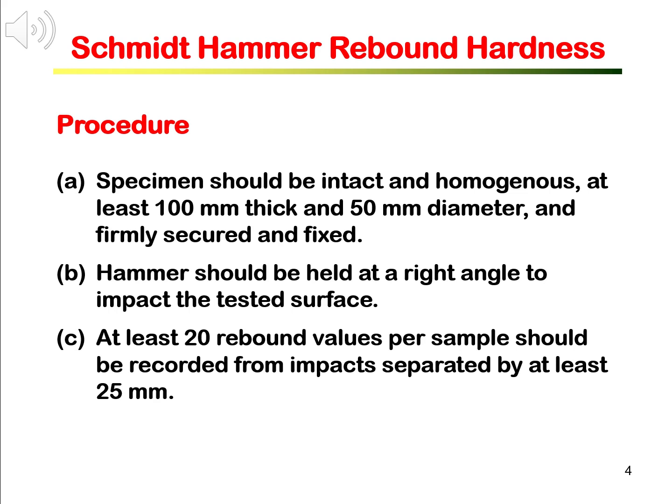Hammer should be held at a right angle to impact the tested surface. After the impact, the hardness reading is shown on the side of the hammer.